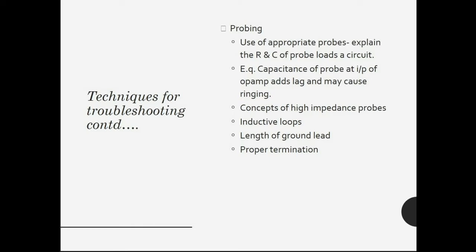The passive probes of oscilloscope. This type of probe is the most widespread, having widespread use. It only includes passive elements and may provide 1:1, that is, straight through connectivity from the point under test to the scope input. Other types may provide a different degree of attenuation. Scope probes are generally classified according to the level of attenuation of the signal.